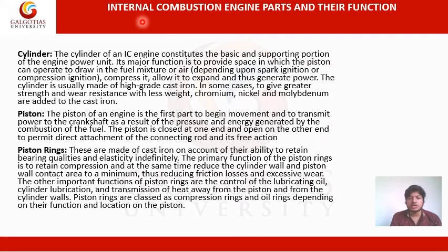Piston rings are classed as compression rings and oil rings, depending upon their function and position. The first two rings are the compression rings, and the third ring is the oil ring, which releases the oil for the cooling of the piston.